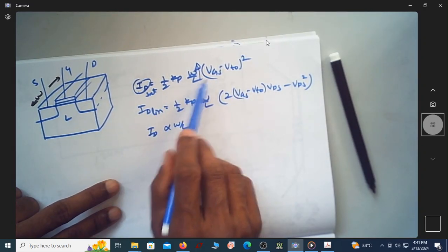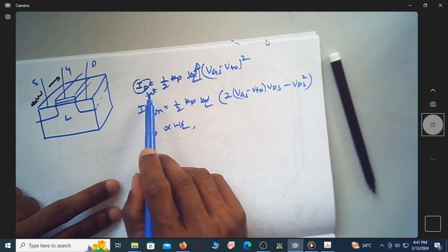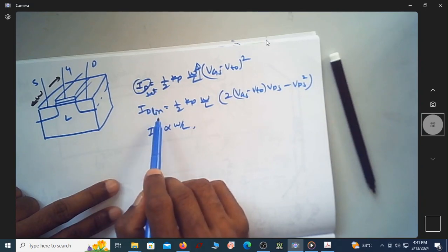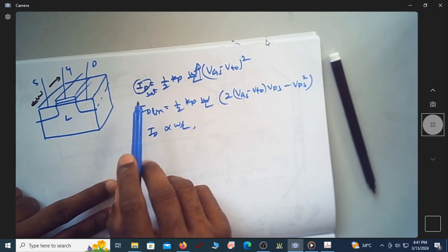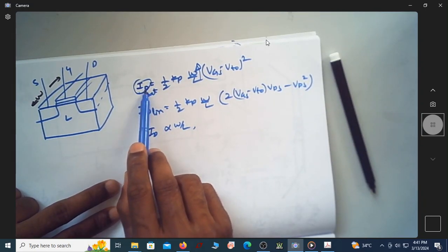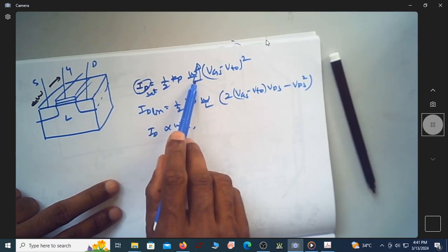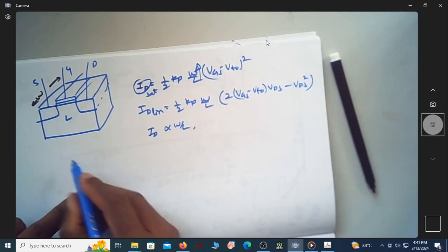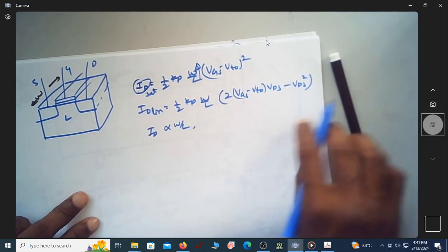The amount of lesser VGS depends on whether it is in saturation or linear region, but anyhow, to get the desired current, if W by L increases, it requires a lesser VGS. The answer is yes, the statement is correct.